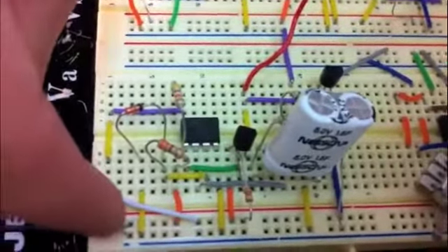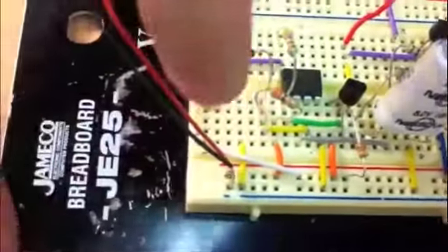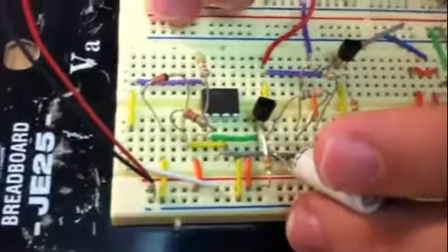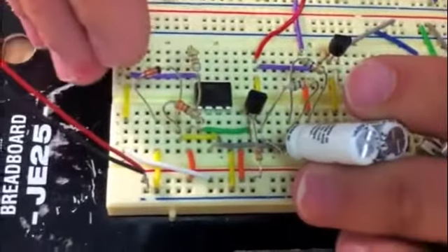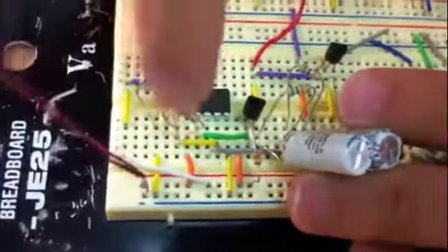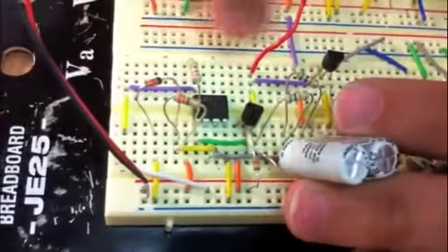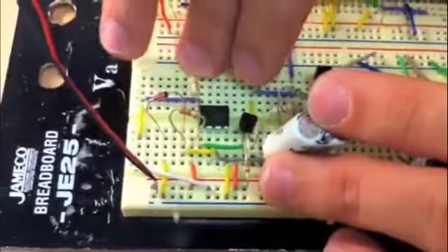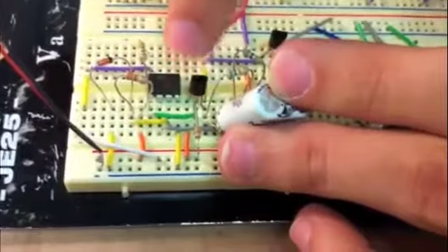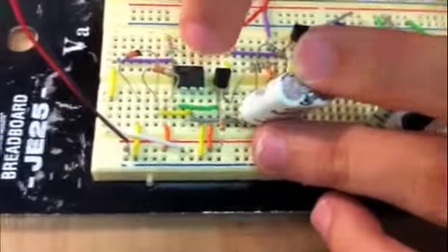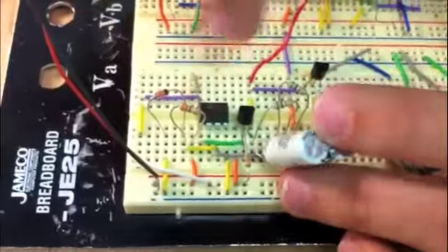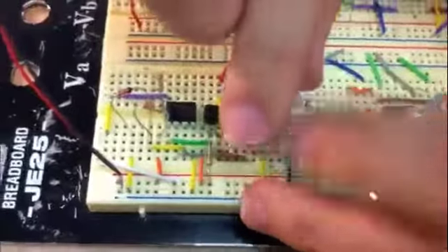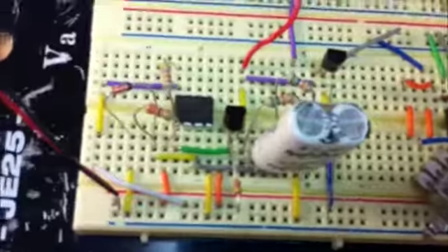The voltage of the solar panel also goes through. Where else does it go? It powers the comparator from the white to the yellow to the purple, and that's where the comparator gets its power source to work. We have the output of the comparator connected to the base of this transistor, which also acts as a switch. With the V minus reading 2.5, you can see the voltage divider here with the gray wire connected to it going to the second pin, which is V plus.